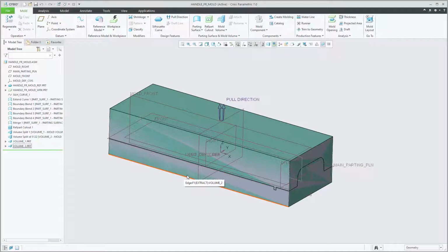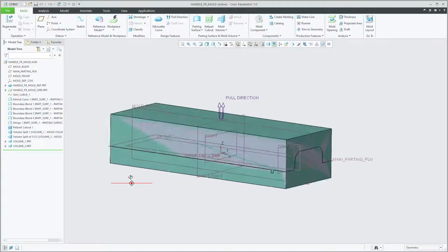One of the solutions that it mentions is you may need to think about venting the mold, so adding vents into the mold to let the air escape. So we're going to look at ways that you might add vents into your mold design in the molding assembly environment here. So let's put a runner into our mold design first.